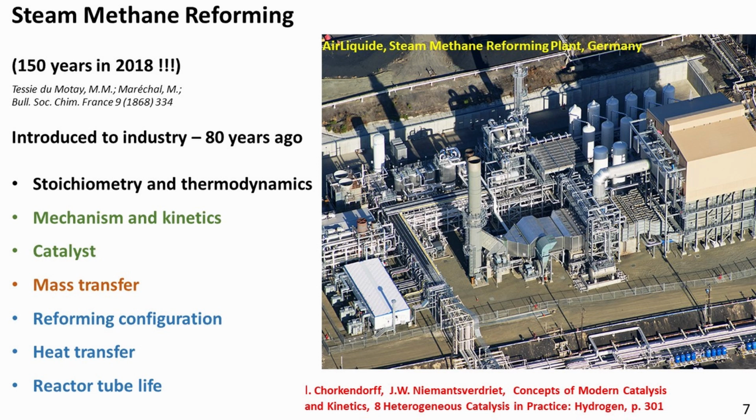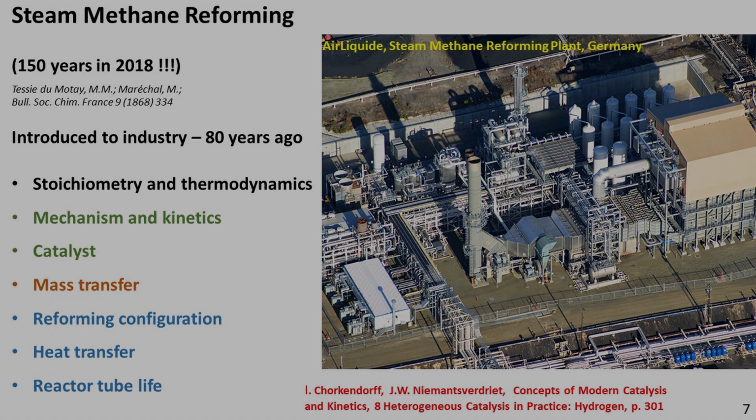The steam reforming process became the preferred technology for synthesis gas for methanol and other petrochemicals, oxo alcohols, citric acid, etc. The progress in steam reforming technology has resulted in a less costly plant, in part because of better materials for reforming tubes, better control of carbon limits, and better catalyst and process concept with high feedstock flexibility. This progress has been accompanied by a better understanding of the reaction mechanism, the mechanism of carbon formation and sulfur poisoning, and the reason for tube failure.